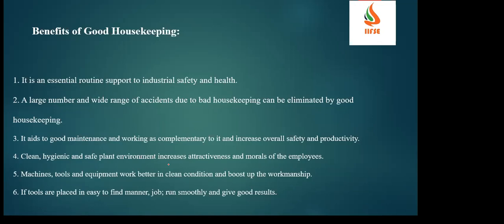So if you see other benefits, it is an essential and routine support to the industrial safety and health. Majorly, it is helpful for the production as well as for the safety and health of the people. A wide range of accidents due to bad housekeeping can be eliminated by good housekeeping. So due to bad housekeeping, we'll have slip, trip, fall, spillages, over inventory, fire and explosion hazard, space congestion, searching time. All of these are causes of accidents that we can avoid by good housekeeping.